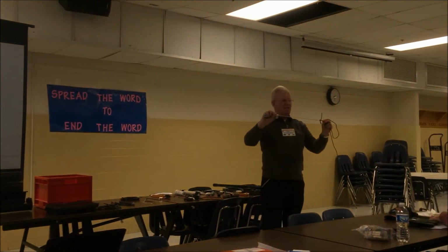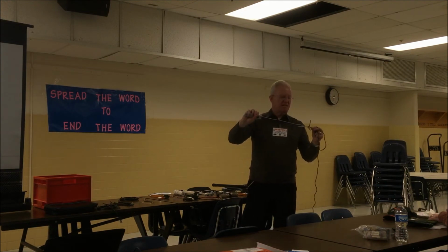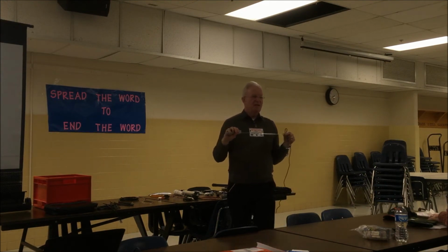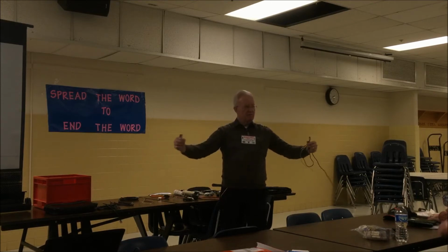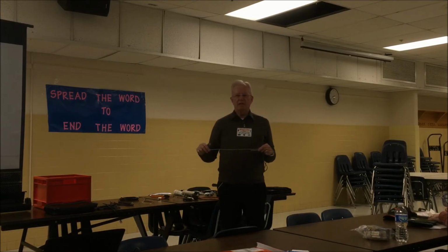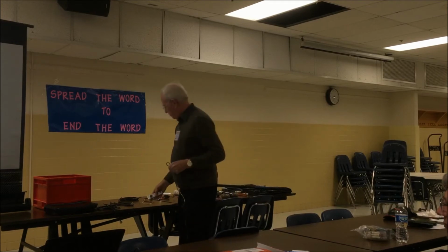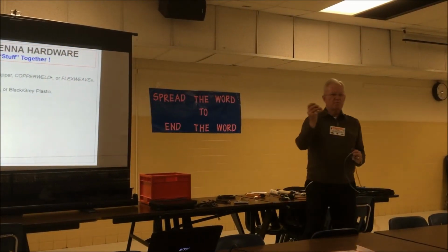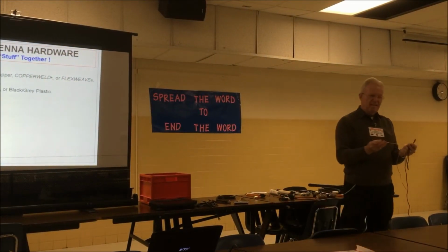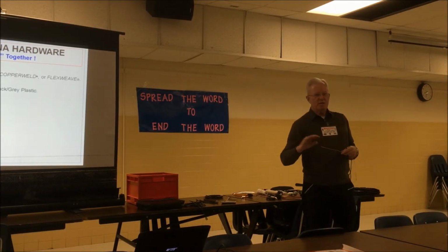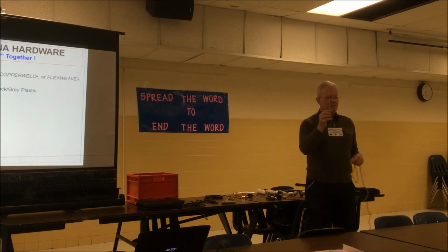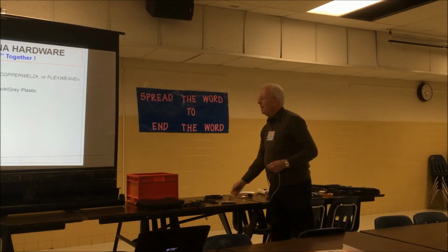So I went and got this, and we made the antennas out of good old what you guys know as lamp cord. Actually, we call it zip cord because it unzips, and it works just fine. Okay. Hard drawn copper. Pretty hard, guys. I don't like to make an antenna with it, and boy, I'll tell you, you kink this while you're pulling it out, you're dead meat. Forget it.